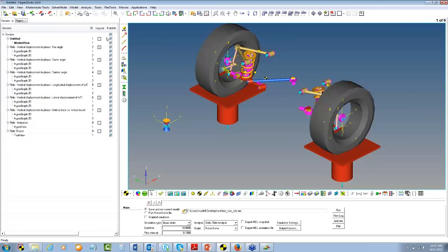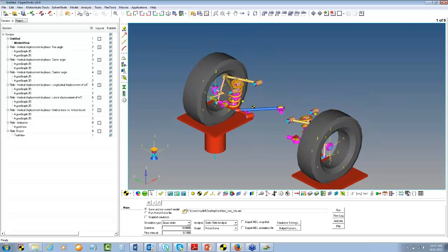Alright, so there was one question about jounce and rebound bumpers. So what exactly are they? In vehicles you have some kind of mechanical stop which restricts the movement of the suspension in case there is lots of suspension travel. When you want to restrict the jounce, it is called jounce bumper, and when you want to restrict rebound, you call it rebound bumper.